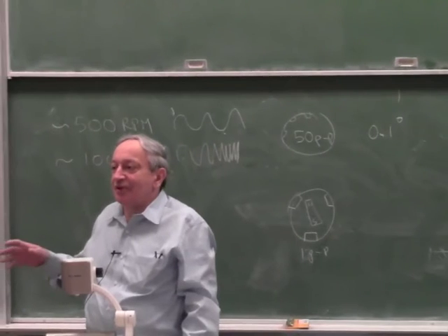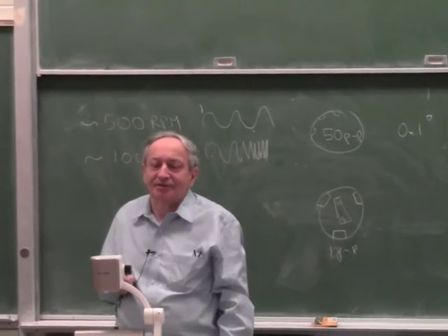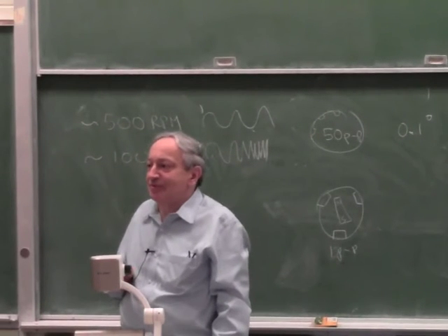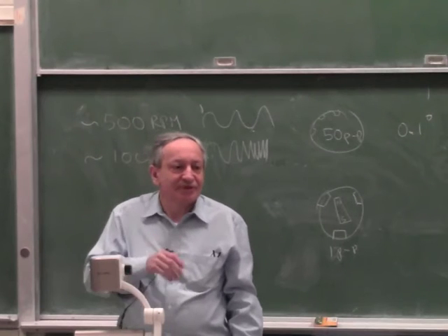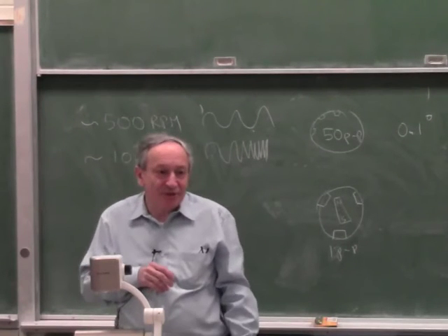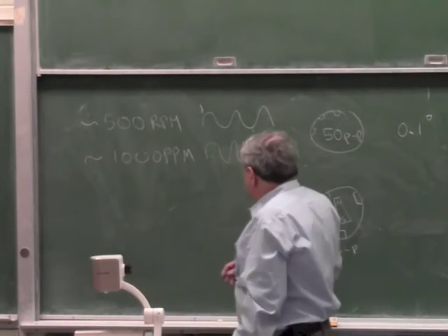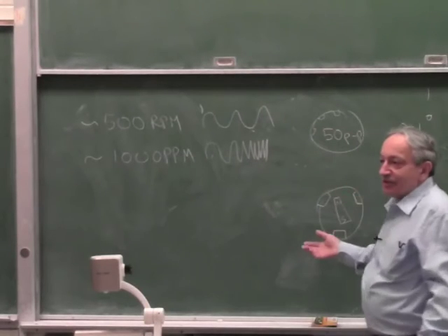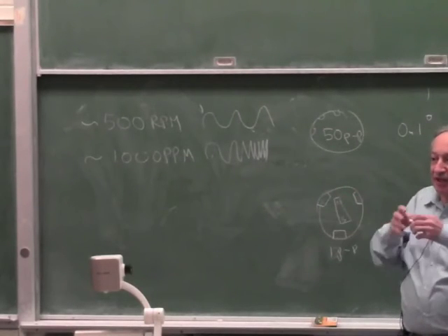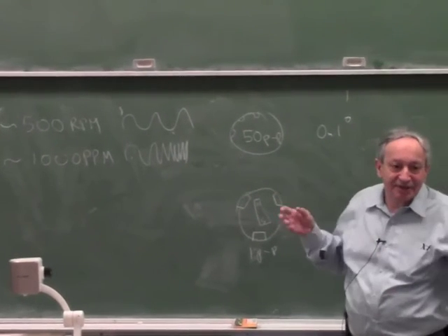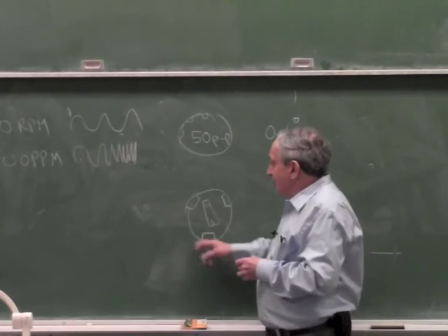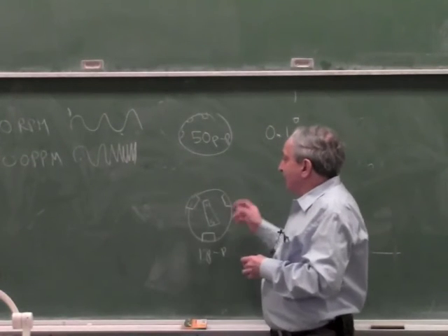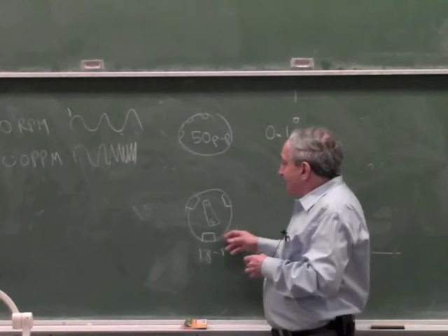I know you haven't seen many of these motors, but maybe you've seen some special projects, spindles. Many thousands of RPM. Basically, there's no limit really. A motor like this can easily run 100,000 RPM. The limit is mechanical disintegration, the bearings. There are mechanical limits. There's really no electrical limit, because if you have the rotating field, you can make it run fast.